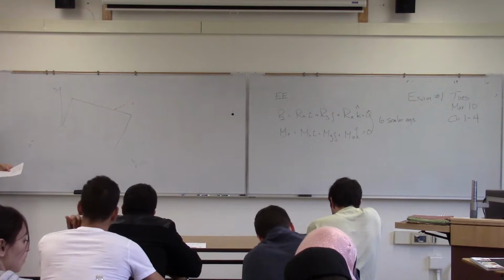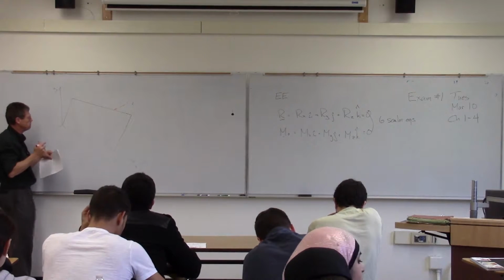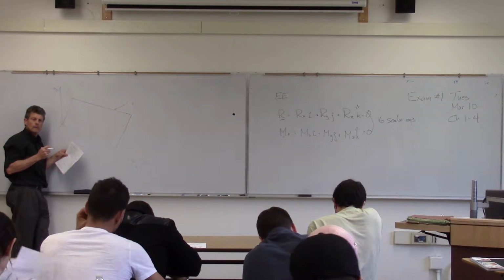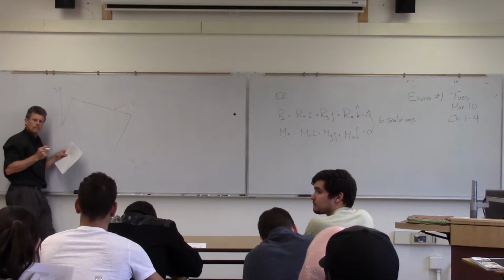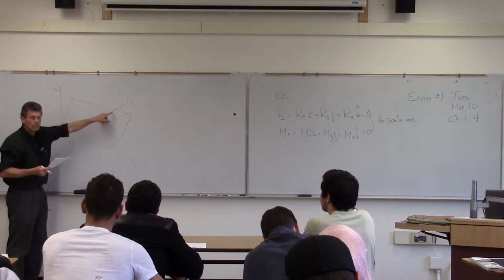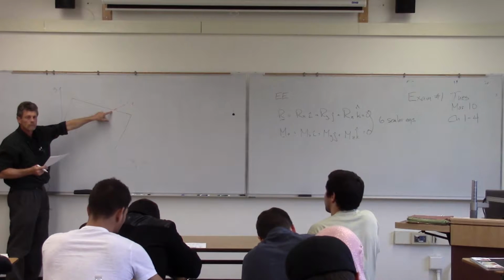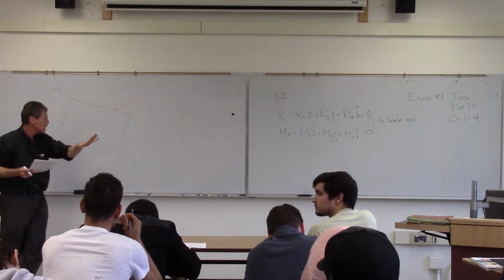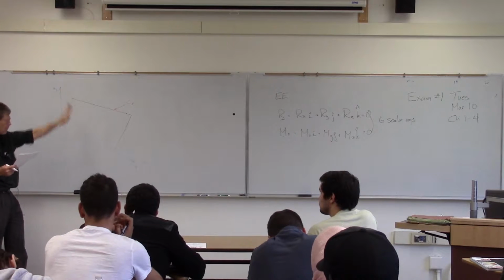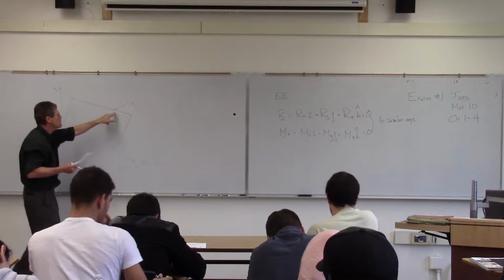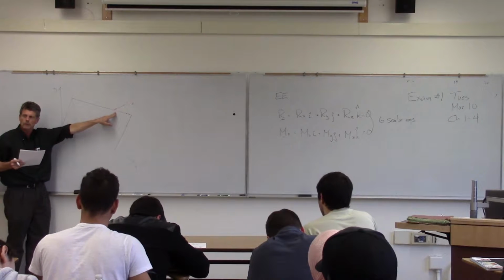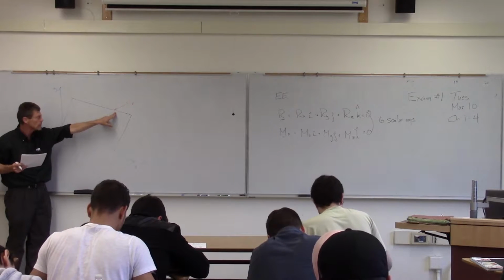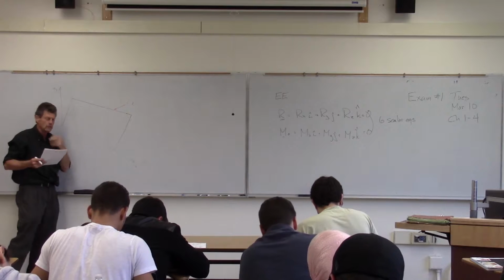Okay, let's think about, we got AY here. What's that? You don't get this? No, what is that? Oh, because that's the pipe. It's leaning against that pipe, yeah. It's a smooth pipe, so there's no friction there, so I'm allowed to slide up and down it and everything. So it's going to provide me support force in that z direction. So I'm going to remove that support and substitute in the force it's acting.